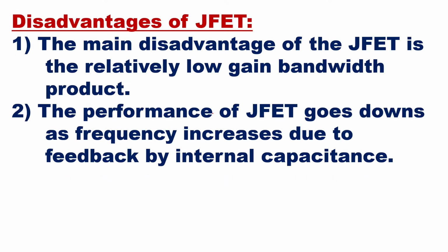Then if you go to see disadvantages of JFET, the main disadvantage of JFET is the relatively low gain bandwidth product. Second one is the performance of JFET goes down as frequency increases due to feedback by internal capacitance.